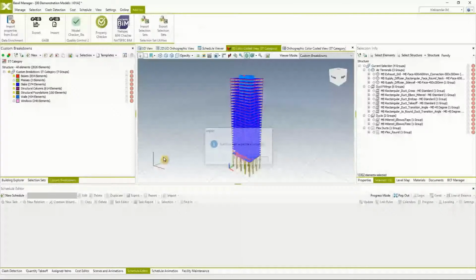We can also test it for, let's say, room name by floors. So we can again repeat this. Let's call it rooms by floor. Repeat the same CBS template. And we're going to see that the coloring scheme is again the same as with the small scale project.